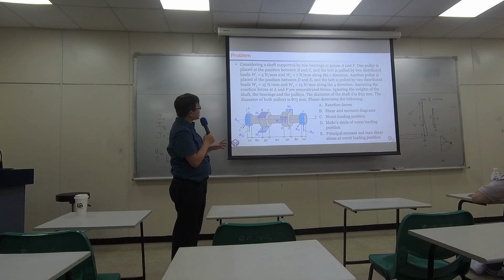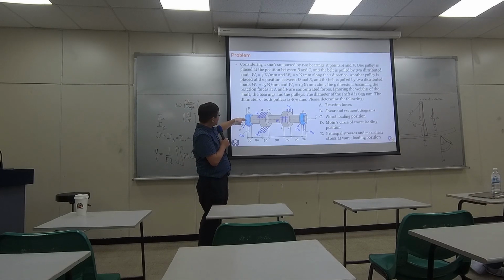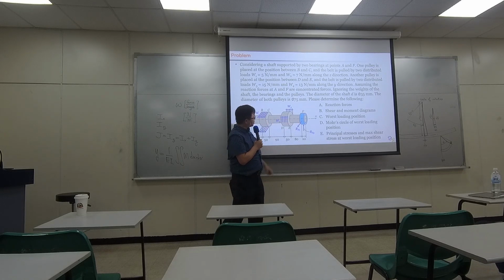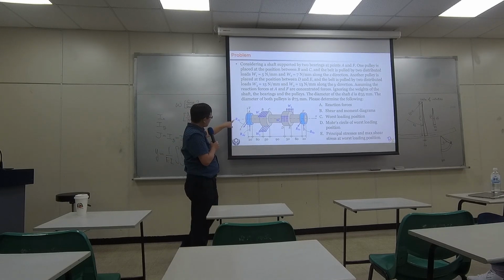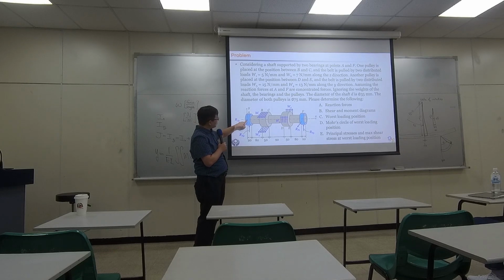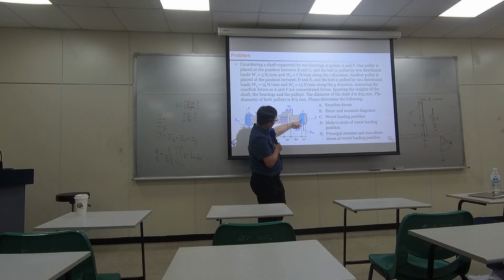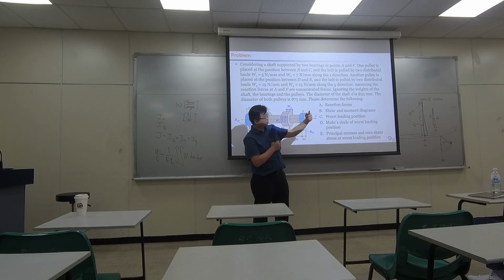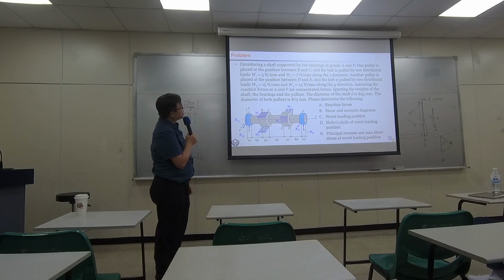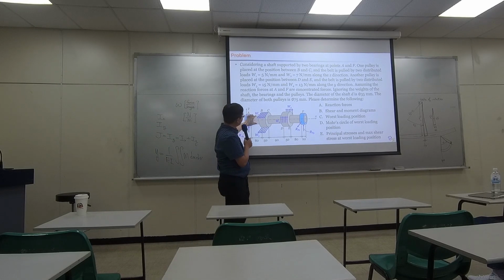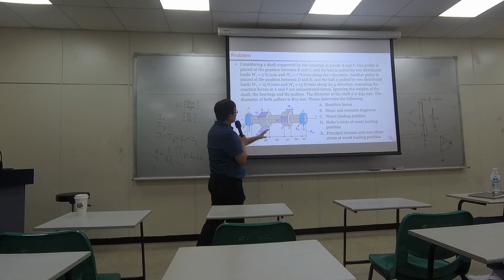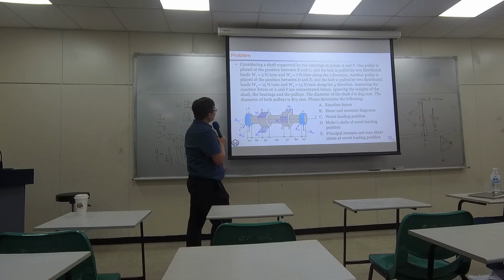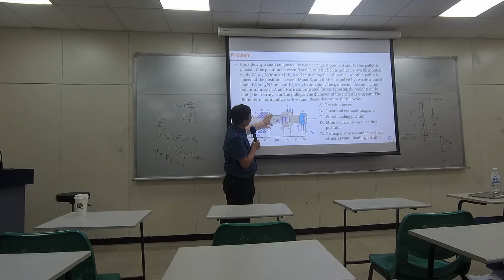And then the reaction forces applied surrounding the bearings are called R. So RA represents the reaction force at position A. RA, the second index Y or Z represents its direction. RAY goes up. RAZ goes toward you guys. RFY goes up. RFZ goes toward you guys. Now the diameter of the shaft here is 35 everywhere. The diameter of the pulley is 75 for both.